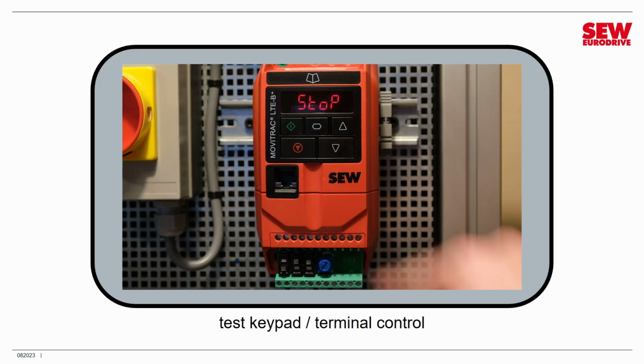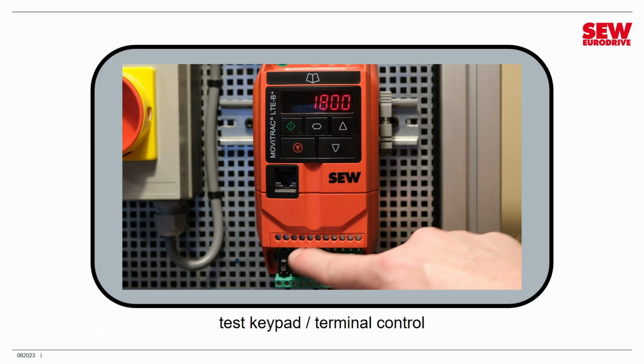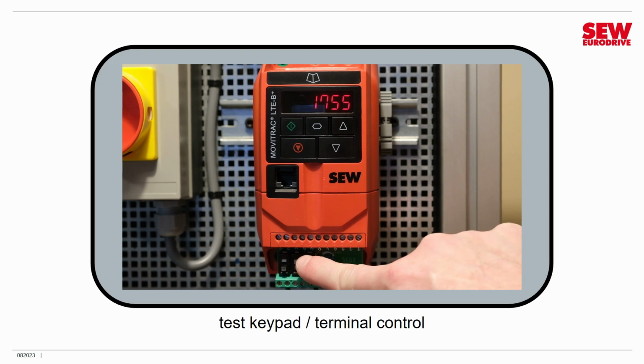I'm going to stop it from the keypad. Now watch this. If I turn DI2 and 3 on simultaneously, it starts the drive, just like the start button. Then I can speed it up. Or slow it down. Or bring it all the way to a stop.